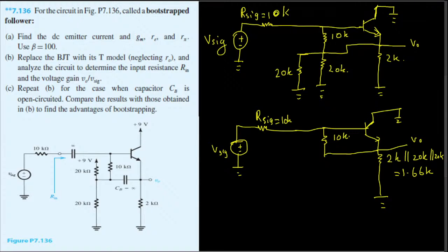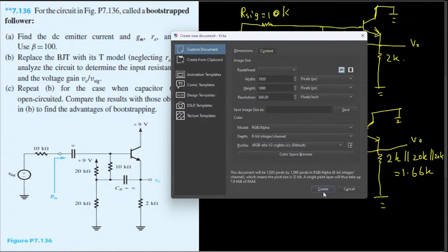And also the collector current, we replace that with gm v pi. Instead of IC, we will put gm v pi for it. And other than that, nothing else will be different. Now let's go ahead and draw the equivalent models. Okay, T equivalent.